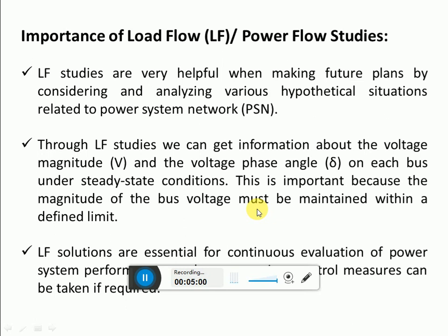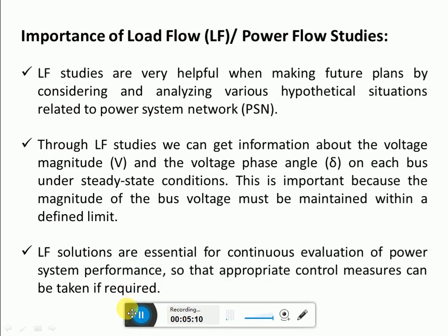So as we are getting this information with the help of load flow, by seeing the situation we can take the necessary action or adjustment to bring the voltage back to its specified limit, or control measures can be taken if required.